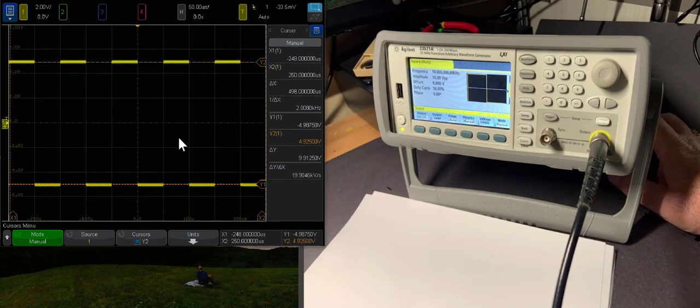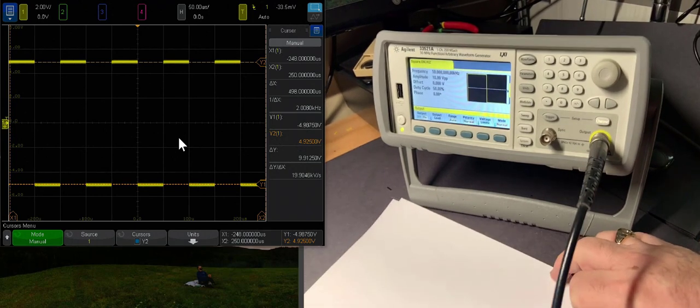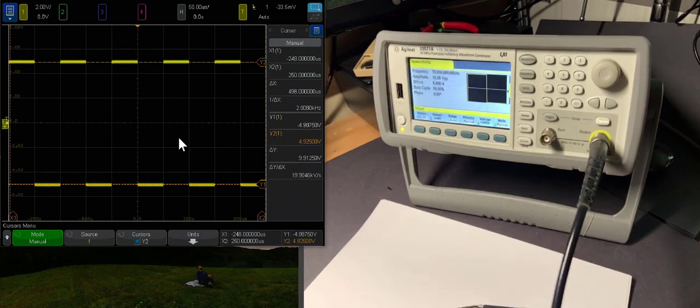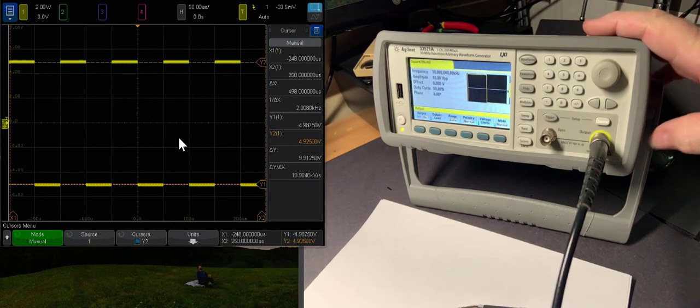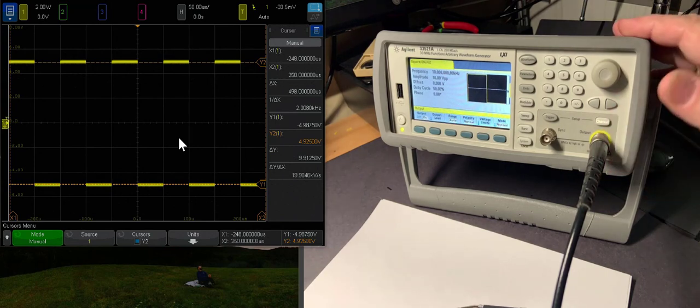The next step is we're going to look at the properties of the voltage source. When we think about voltage sources, we think typically of a 0th order model. The absolute simplest model of a voltage source is an ideal voltage source. And one of the properties of an ideal voltage source is that the voltage output is always constant. It doesn't change no matter what the load is that we apply.